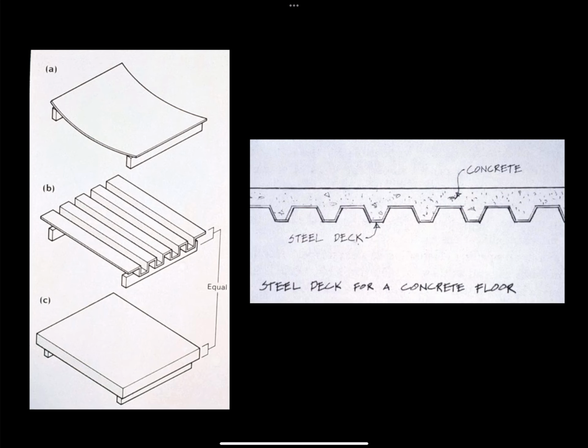If we have a thin sheet of galvanized steel, as you see at the top, it's floppy. It doesn't have any structural spanning capacity, but when we corrugate it, it becomes very stiff, and it's still just a thin piece of galvanized steel, so it's very light in weight. But it can span, and it becomes the permanent formwork then for a site cast concrete slab.